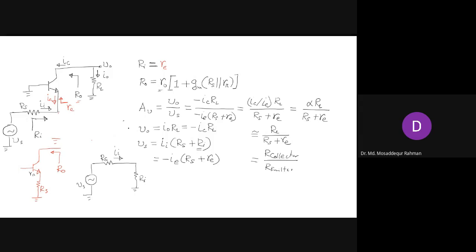So that is the voltage gain for the common base. And then finally the current gain, which is actually pretty straightforward. This I naught by I is minus IC by minus IE. Minus and minus cancel out. IC by IE is alpha, so that is almost equal to 1.